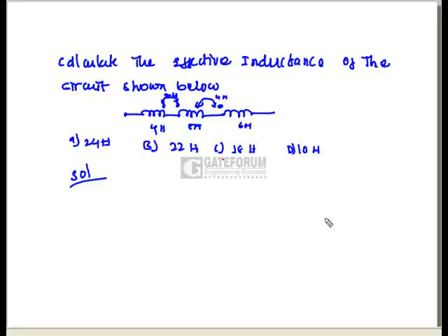So that's why between the 1 and 2 inductances there is a series opposing nature. Between 2 and 3 inductances there is a series aiding nature. The formula for series opposing is L1 plus L2 minus 2M, and series aiding is L2 plus L3 plus 2M. Right, but here 3 inductances are given, so initially these are three in series.